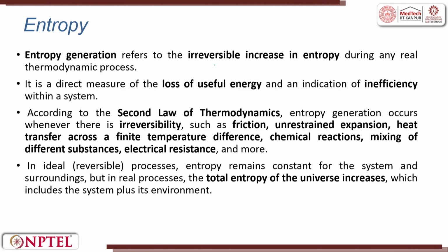Entropy generation refers to the irreversible increase in entropy during real-time thermodynamics. It is a direct measurement of loss of useful energy and indicates inefficiency within a system. According to the second law of thermodynamics, entropy generation occurs whenever there is irreversibility, such as friction, unrestrained expansion, heat transfer across a finite temperature difference, chemical reaction, mixing of different substances, electrical resistance and more.